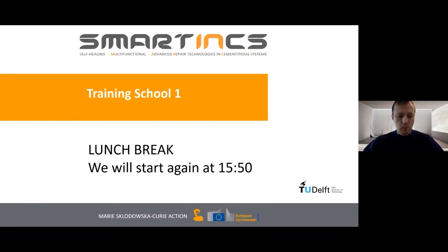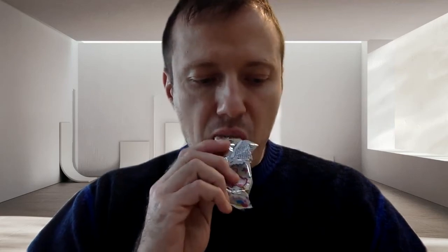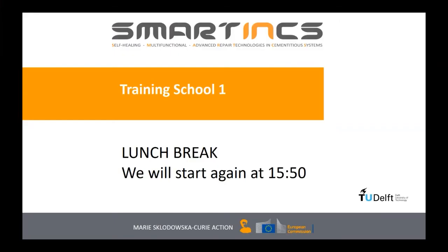So actually, I did some modeling on the crack self-sealing of mortar with superabsorbent polymers. And basically what I do is that I simulate the evolution in time of the superabsorbent polymer swelling, and then how elements that before were belonging to the crack space that had certain transport properties, once they are occupied by superabsorbent polymers, they become superabsorbent polymer elements with certain transport properties that will influence how, for example, if you are simulating, in my case, capillary absorption of water, how this piece of crack that was a crack before but now is occupied by a healing agent, then how does it reflect on the transport in the crack? So this is a way that you can do it as well.